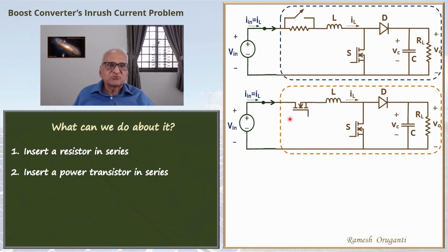The power MOSFET has three terminals: drain, gate, and source. Increase the gate to source voltage slowly. The main current between drain and source slowly increases. The device goes through the active region and turns on slowly. That will ensure that the capacitor is charged more slowly and the surge of current is avoided. After a certain delay, the MOSFET is fully turned on.